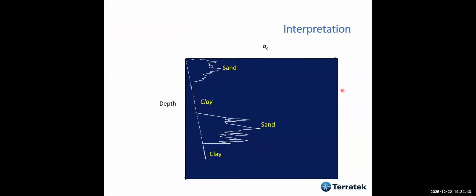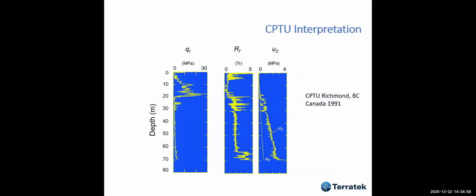When I start looking at the CPT data, we only have this. We had sand if this QC was hard. We have clay if QC was low. Sand and clay, that's what happened. And then it was developing with time. And in 1991, that's what I used to do. I used to do my own plots. There were graphs that we could classify the soil.